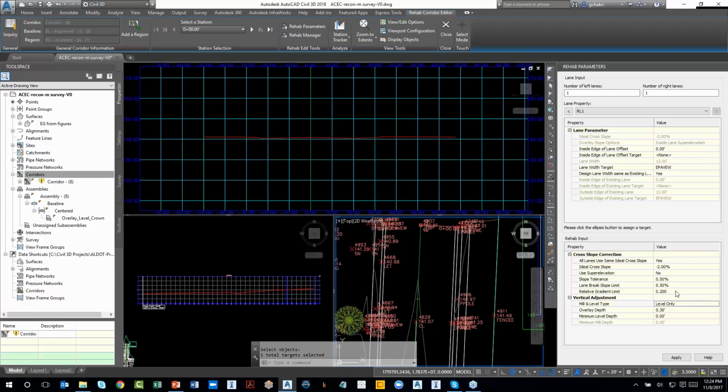In cross slope corrections, if your ideal cross slope is 2%, let's say, which is where I specified here. And if your existing ground happened to be 1.8 or maybe 1.3%, so too flat, right? Whereas you wanted to have ideal cross slope as 2%. So if you are holding exactly the same profile point, you are actually going into a milling condition, even though you didn't ask for a milling kind of thing, right? So at the center line, no milling, but as you go to the edge of pavement, you are going to deeper and deeper milling. So maybe you don't want to have too much of a milling, right?